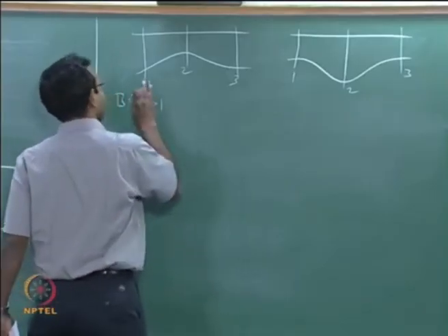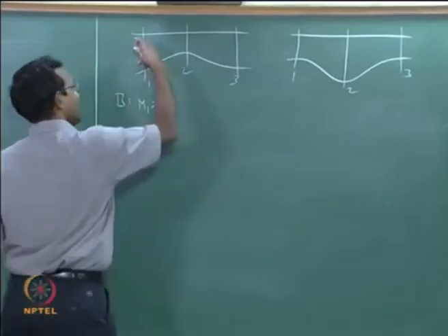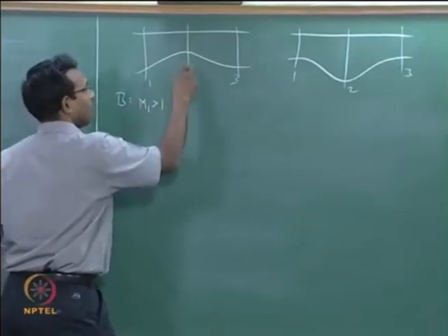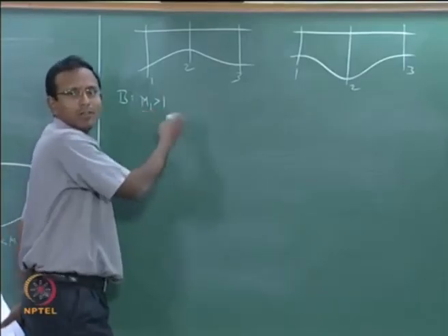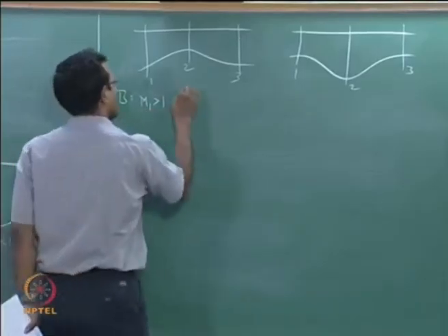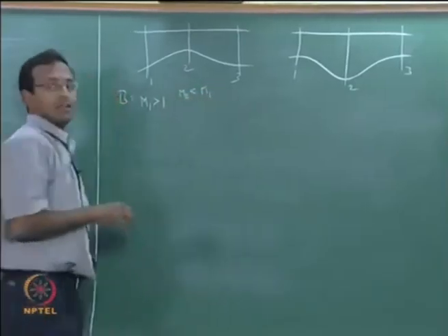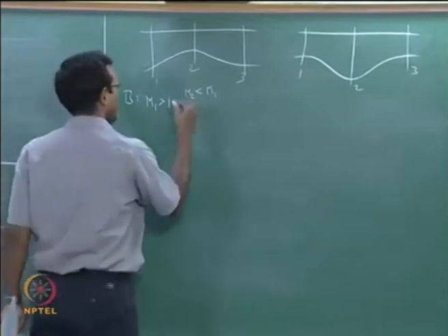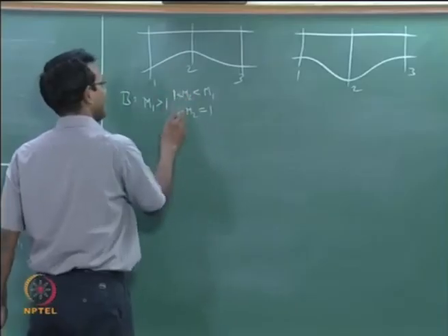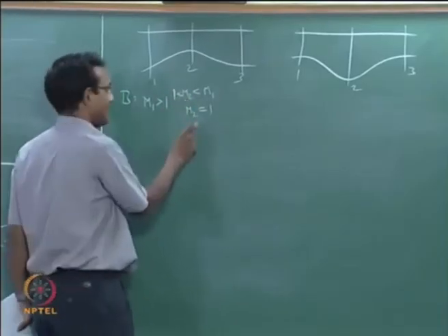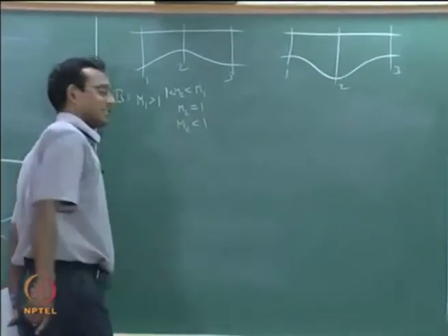I like this statement. Anyways, you have to get used to something in compressible flows. It is supersonic, so it is going to go towards m equal to 1, which means 1.5 will go towards 1. Maybe it will become 1.1, I do not know. All I can tell is m2 less than m1. Let us consider another case where m2 is specifically something like 1.1, and here it is exactly equal to 1. Can I have a case again with m2 less than 1?